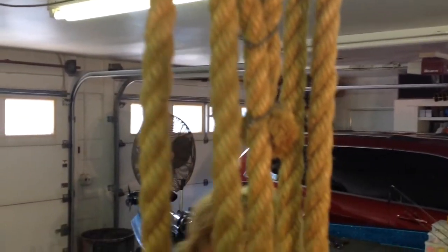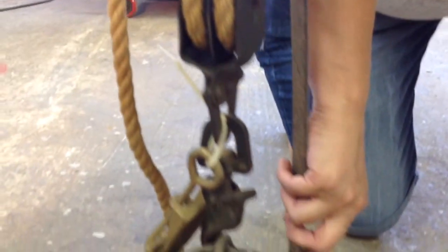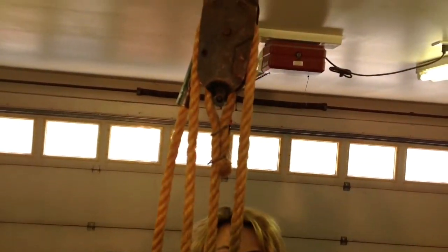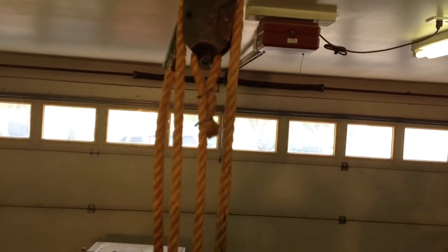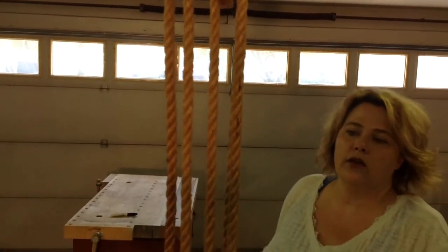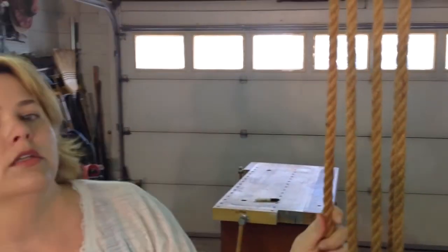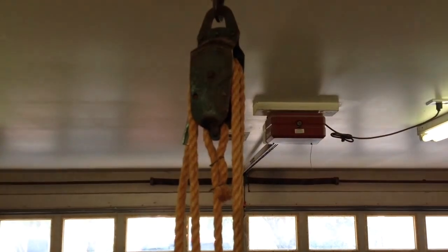And then I'm going to measure the distance at the bottom. How far from the floor did it raise up? So going down here, kind of steady it a little bit. Yes, it is 3 inches. So it raised from the floor to here 3 inches. And then I had already pre-made the marks of 1 foot, which is 12 inches. So I can do that mathematically, and that comes out to 4. So my ideal mechanical advantage for this block and tackle, this particular one, is going to be 4.